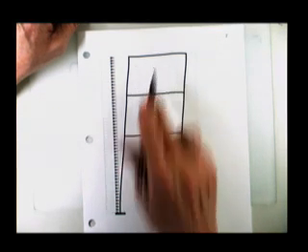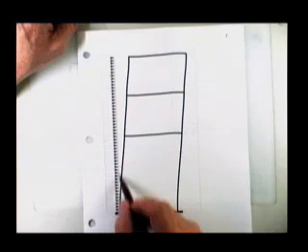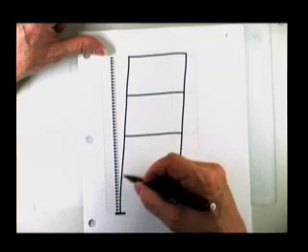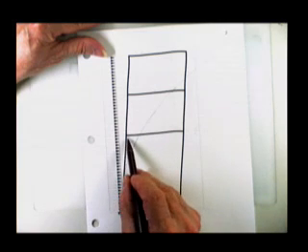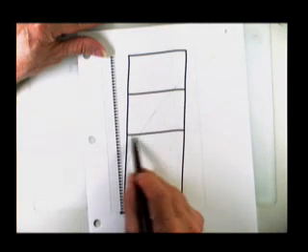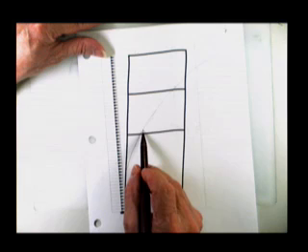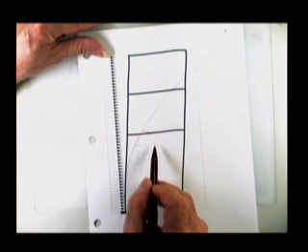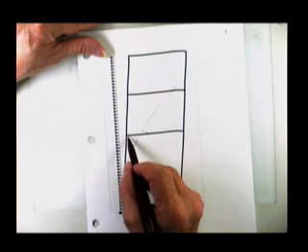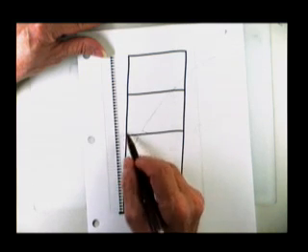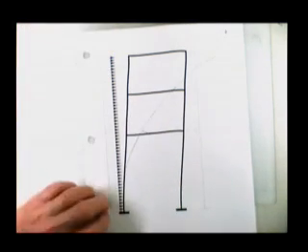These floors would move to the right. These things would like to kind of bend like a cantilever. However, because of this member here not liking to bend, it's going to have to come in at a right angle. And since it doesn't like to bend, I have shown a little reverse curvature around those points.